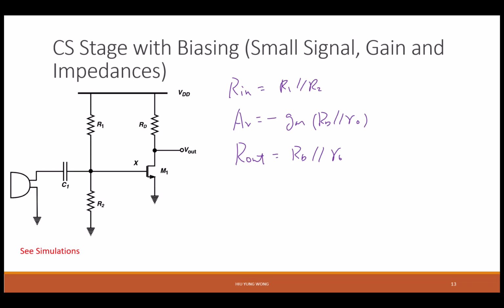Yeah, so he said, then let me set R1, R2 to be really high, then it's almost like infinity, right? And then the trade-off is that you need to have a large resistor. And if it's an integrated circuit, it occupies a lot of area. And then, of course, it has noise. If you go to noise analysis, a large resistor generates a lot of noise.